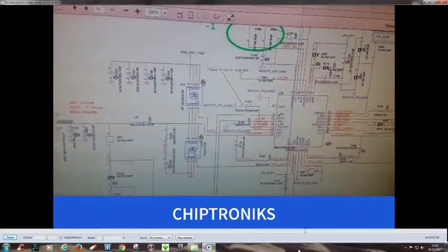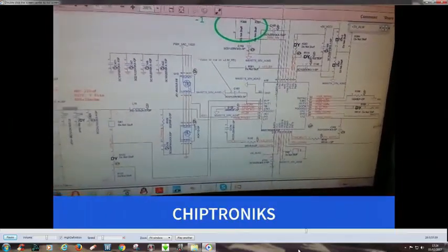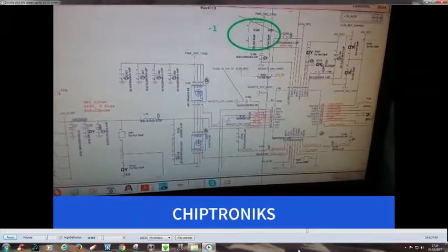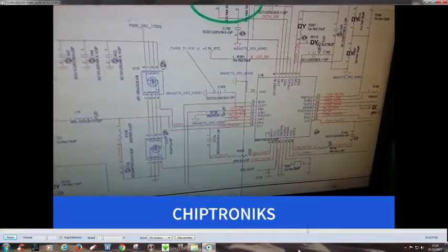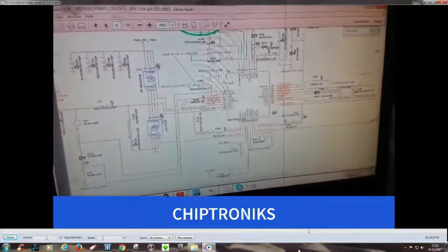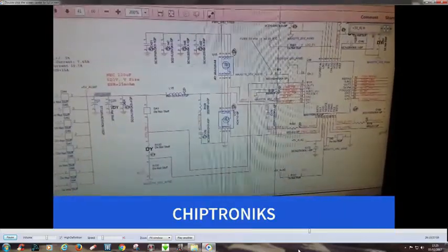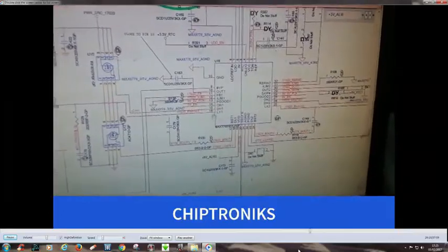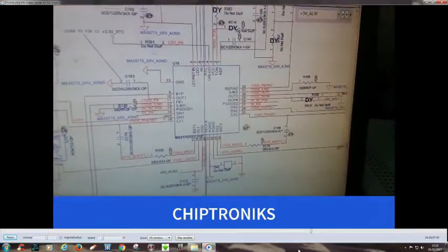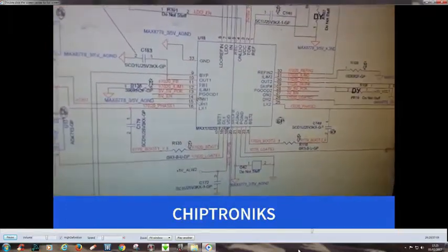So we'll go to find this U18, the 3 volt 5 volt regulator IC, and we'll check all the things. That is ON1, we'll check the 5V_EN at this pin. Analyze this 3 volt 5 volt regulator IC, how this is working, and we'll check the voltages on this motherboard. And you can see there are two voltage limiters, one side 5 volt, another side 3 volt.